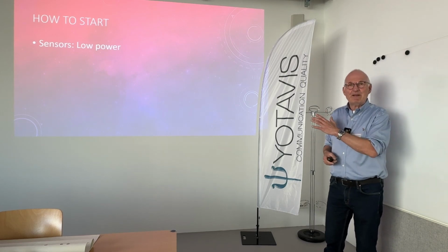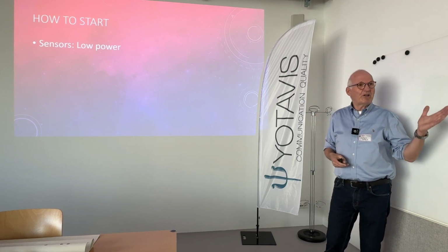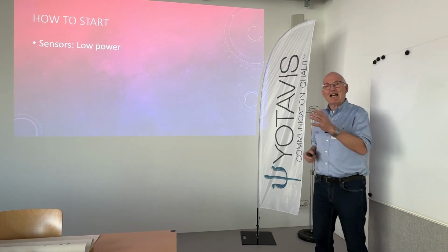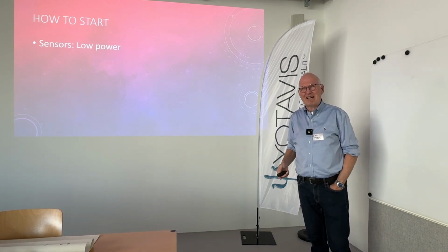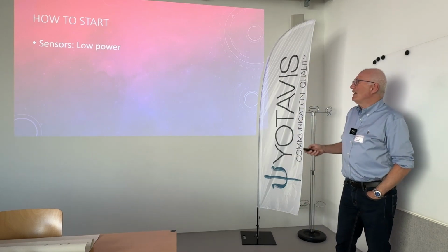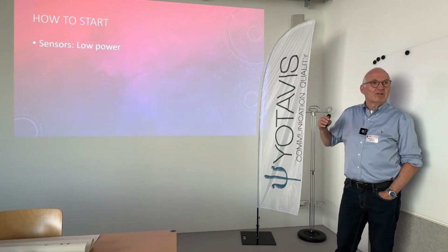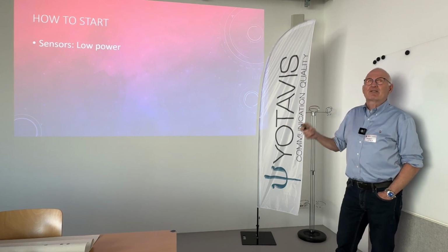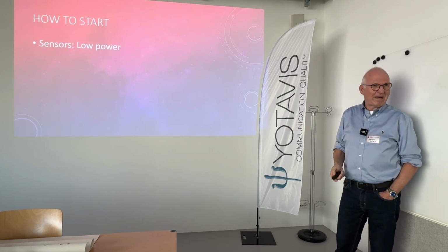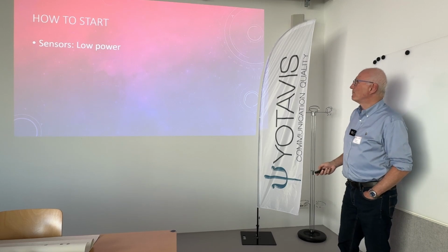And an SF12 message is easily 1.5 seconds. So you can imagine how much is left for the 24 hours in between. So that is very important. If you want to tinker with LoRaWAN, you need to understand low power design.